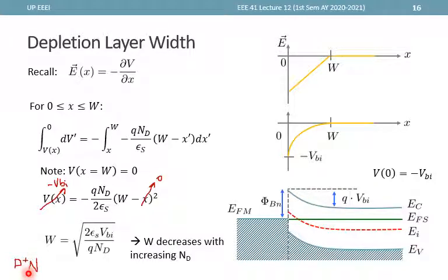So if we have an MS contact where the other one is a p-type, so if we have MP, most of the equations can be made in parallel or compared to that of an n+p junction. Okay, so these two must be similar in format, and MN must be similar in format with this p+n.